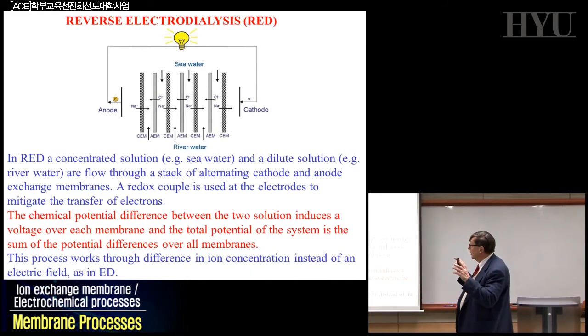If you are able to improve the system, for example, instead of using seawater, we put brine here. Instead of 0.6 molar, we put 6 molar, not 0.6, 6. That means one order of magnitude higher, against fresh water or river water. So the power density is no more 0.61 watts per square meter. It can be, for example, numbers that here in Korea or in Japan are suggested, about 21 watts per square meter. With 21 watts per square meter, if you build a huge power station, that becomes quite interesting and competitive. But for doing this, you need a membrane that can work with 6 molar.